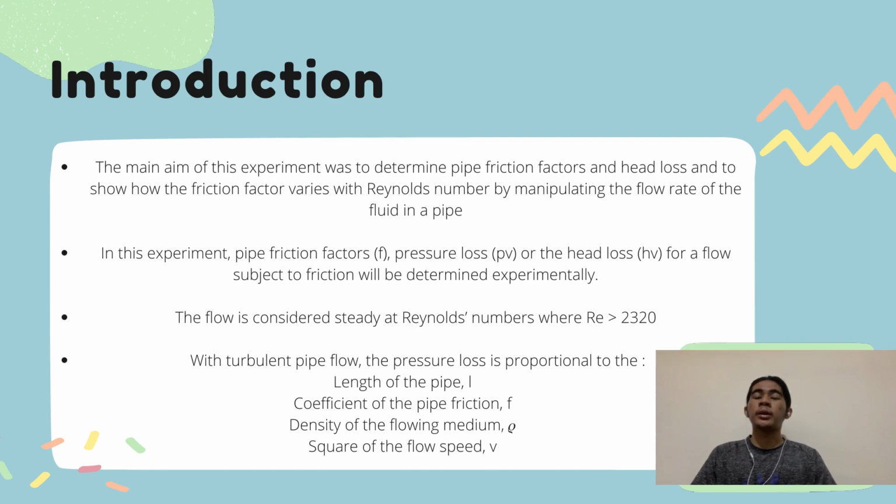In this experiment, the pipe friction factor, pressure loss or head loss for a flow subject to friction will be determined experimentally, and the flow is considered steady at Reynolds number where Re is bigger than 2320. With the turbulent pipe flow, the pressure loss is proportional to, first, the length of the pipe. Second, the coefficient of pipe friction. Third, the density of the flowing medium. And fourth, the square of the flow speed.